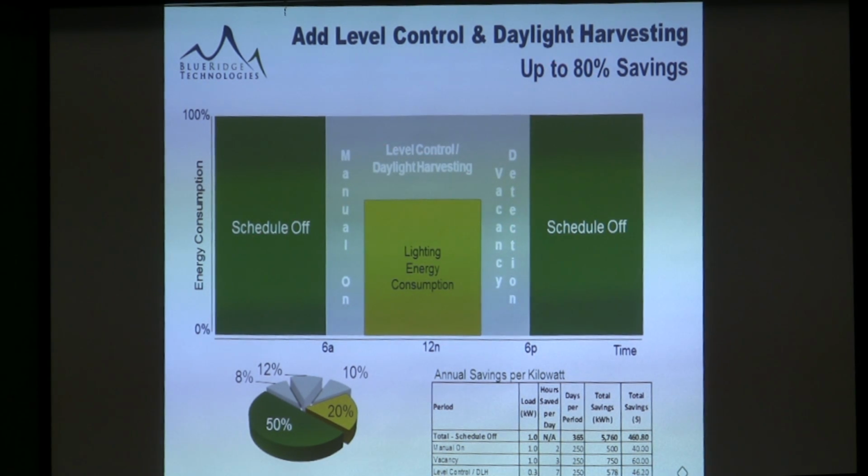And you may hear that term from other lighting control folks who compete against us. But one thing that I'll tell you is you start looking at this particular chart here, and most of the savings is coming from the bookends. And as you get into the middle of the day, not only are those savings less, but they're harder to reach. So your ROI starts to get extended. I've seen daylight harvesting systems that have been proposed in the 15 to 20 year payback range. And not a lot of customers buying that.